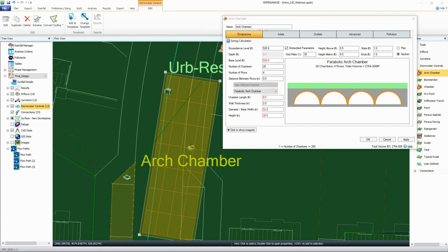And it's the point, but it's something for the O&M plan. It's not just, okay, we bought washed sand and some filter material, we're done, we planted some plants and great. Just as long as you trim those plants back reasonably every 6 months, you're good for 60 years. No. What you might want to do, and some cities are starting to do this, is your O&M plan is to replace that soil. And that will probably have to go to a special landfill, because it's probably going to have heavy metals in it.